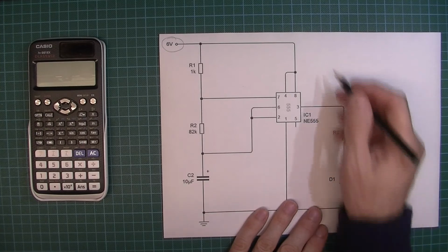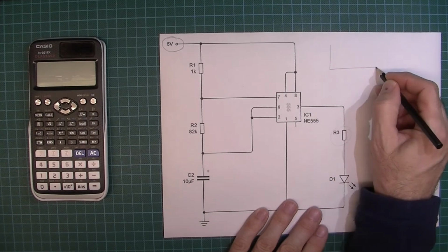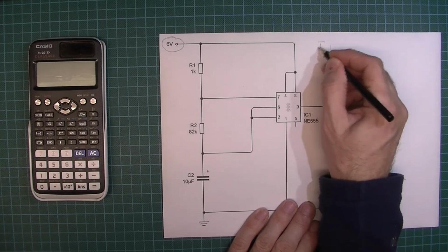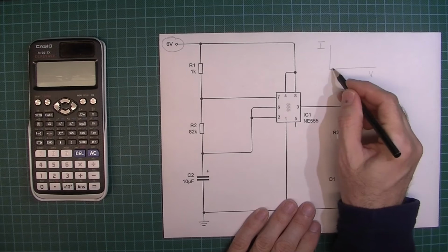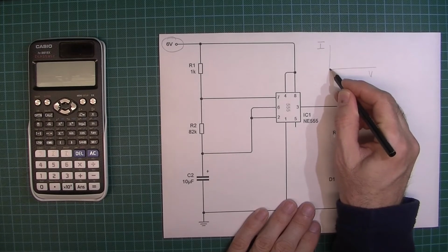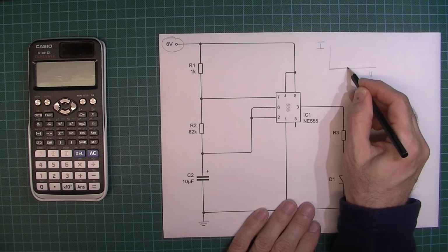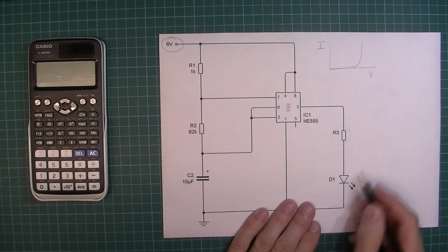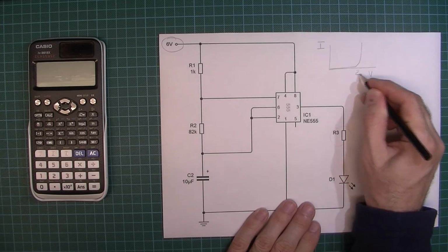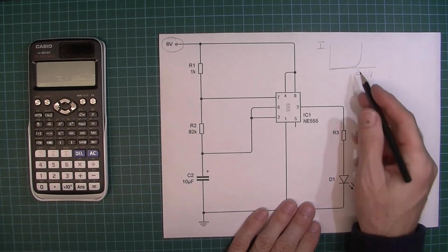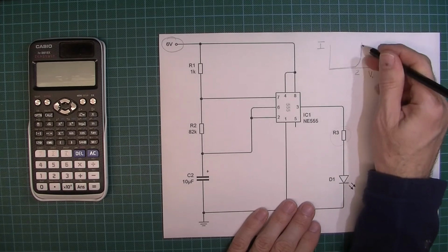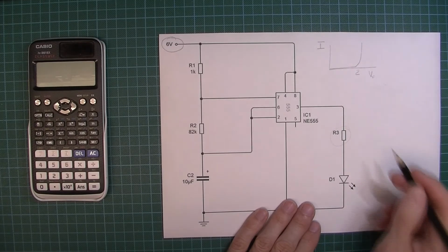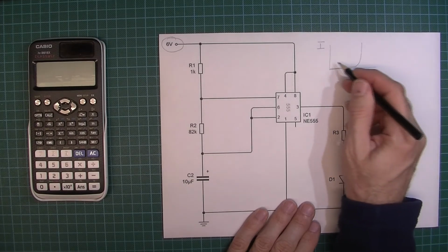If you were to look at the datasheet for an LED, you would see something like this, where voltage is on one axis and then we've got current here. We call it a characteristic curve for the LED, and the current stays very low until a certain voltage is reached. That certain voltage for a red LED is about 2 volts. It's actually probably more likely about 1.8 volts, but 2 volts is good enough for us. Once we get up to that forward voltage, the voltage stays at about 2 volts, but then the current increases dramatically.